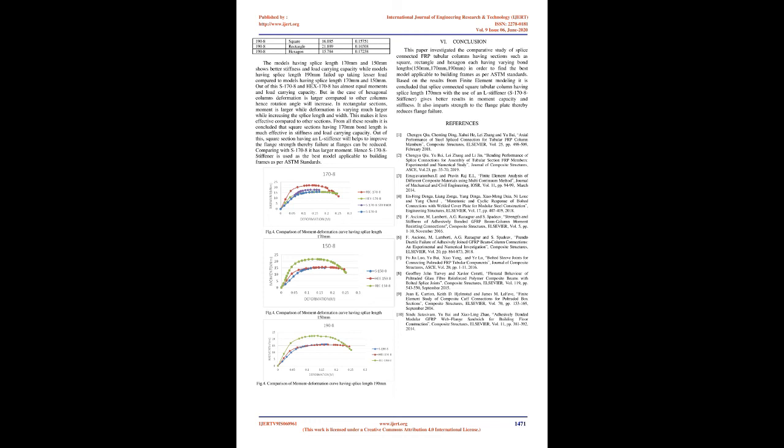Out of this, S170-8 and Hex 170-8 have almost equal moments and load carrying capacity. But in the case of hexagonal columns, deformation is larger compared to other columns, hence rotation angle will increase. In rectangular sections, moment is larger while deformation varies much larger while increasing the splice length and width. This makes it less effective compared to other sections.